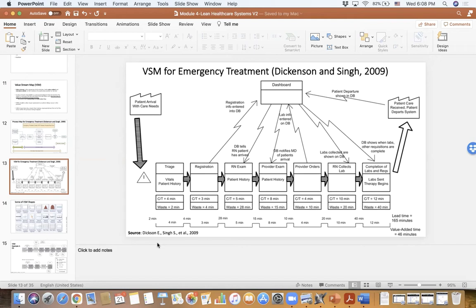The whole framework or roadmap associated with value stream mapping was to develop a value stream map of the current state of the system, analyze it, get a better sense of what is happening, what are the potential areas that can cause the problems that you're observing, what are the potential areas that can be improved or changed, and then, based on this analysis, develop the future value stream map. Once that future value stream map has been approved, go ahead and implement it.